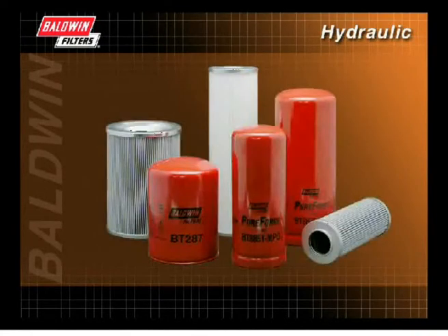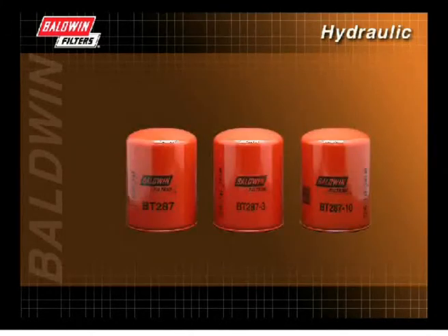A lot goes into choosing the correct hydraulic filter, and Baldwin provides an extensive line of hydraulic filters which meet performance requirements on all types of operating systems. Spin-on hydraulic filters, such as the Baldwin BT287 series, are typically used on the return side on low-pressure hydraulic systems.